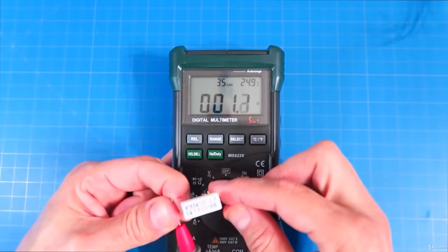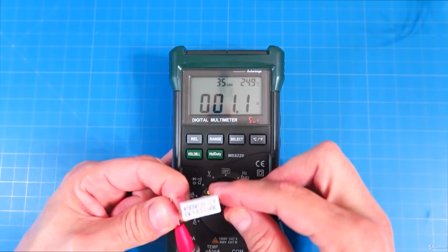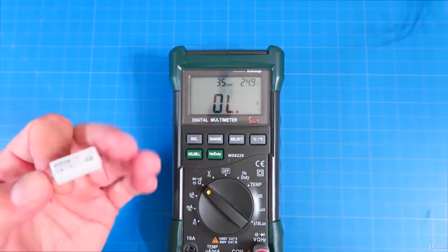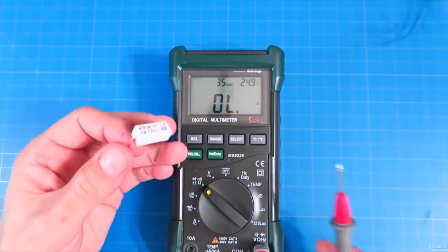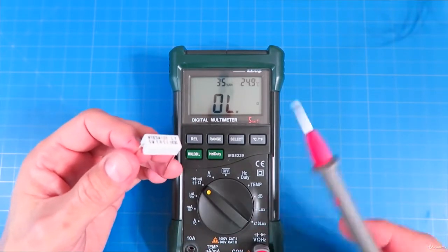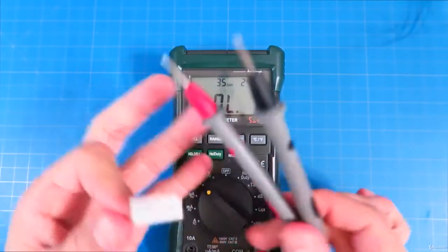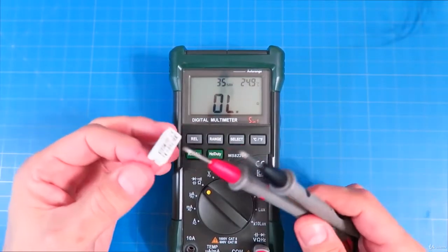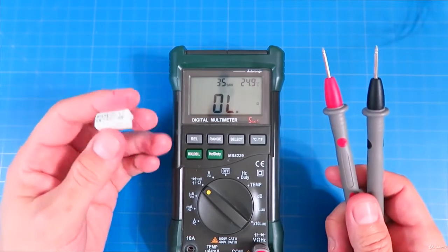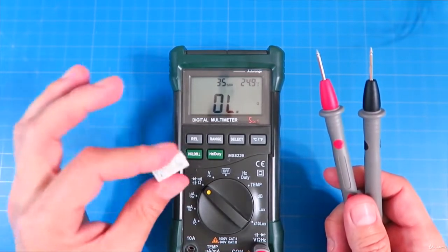And now it's getting more accurate here. So it says it's 1.1 ohms. All right, now these devices to measure this, it runs a current through it, and then it senses the voltage through the same cables. And this is a little bit inaccurate. So when you start getting down to very small values, it's harder to measure them.